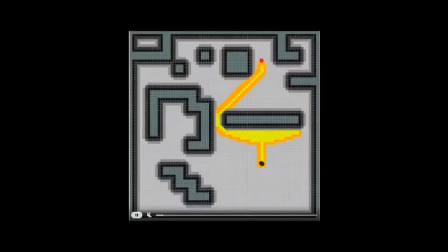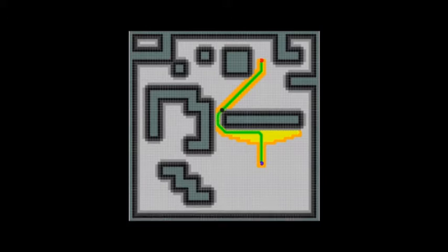And a lot of the other algorithms, like greedy best first search, expand the nodes, the cells, with a bias that just looks to the front of the robot, not considering backward, and use the Manhattan distance or the Euclidean distance as a parameter to say okay, go here and don't go to the other side.